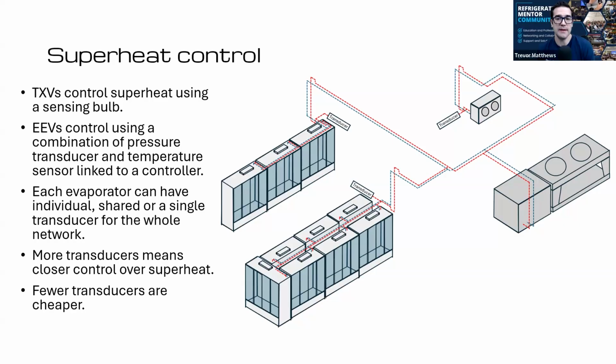Yeah. And that's it. It's easier for troubleshooting. It is more upfront cost for the end user. But with CO2, which I am loving, there are so many more trends that we can get in the controls. So you can look at an actual system. You get the superheat, you get the suction temperature, suction pressure, you get the discharge air, the supply air, the defrost termination. And this stuff we did, it's not new to the industry.